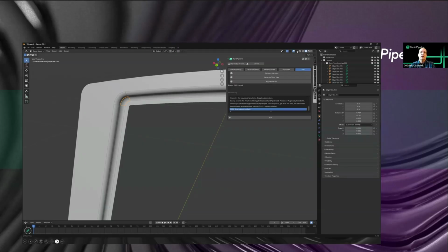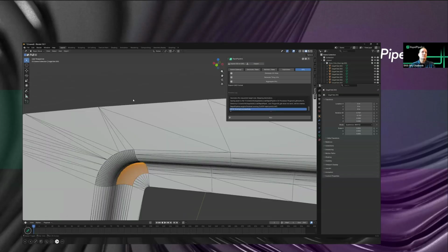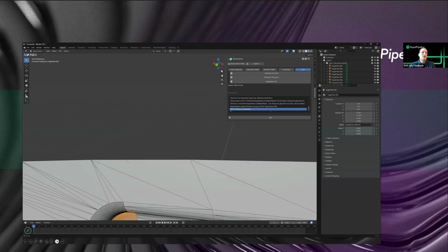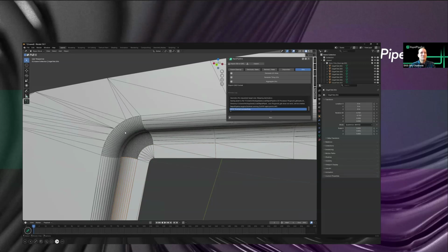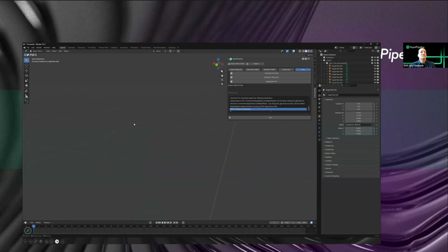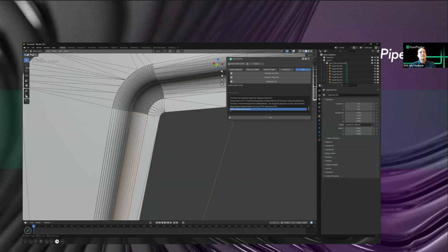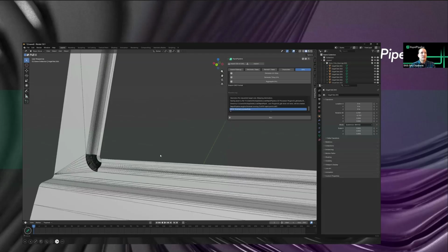The other thing here is if we turn on geometry, we'll see that some of these patches are super high resolution and some are super low resolution. It really depends on the surface itself and how it was made, how it's going to actually be tessellated. Because these are all separate, they're all tessellated to a different resolution, and you end up with differences in the way that they're tessellated. Sewing basically automatically takes care of that.